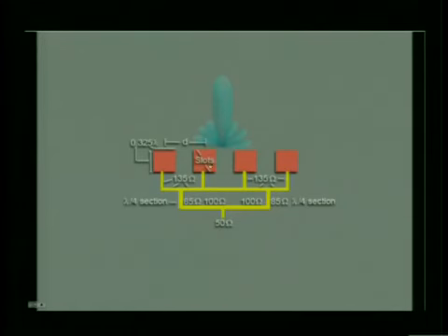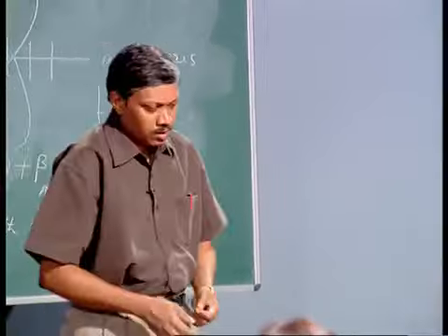And if I say this is the axis of the antenna, then I have a radiation which is in this direction, the perpendicular direction. So, this is a broadside radiation. Okay. You mark, there are certain side lobes also, minor lobes, but this is the situation.